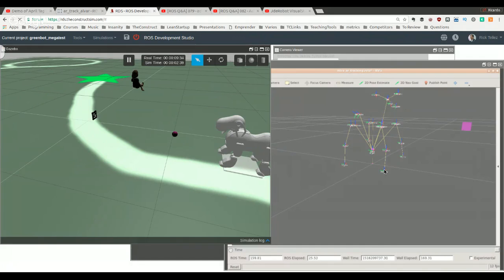So we have here a system that uses the camera of the robot and the AR Track Alvar packages in order to make the robot detect those tags. Now, the final step is to move the robot in the direction of the tag. That's a very simple planner that we are going to do, very, very simple. You can modify that, you can include other planners and integrate them. That would be nice to see in case you try it, okay? We are going to show just a very simple controller for that.